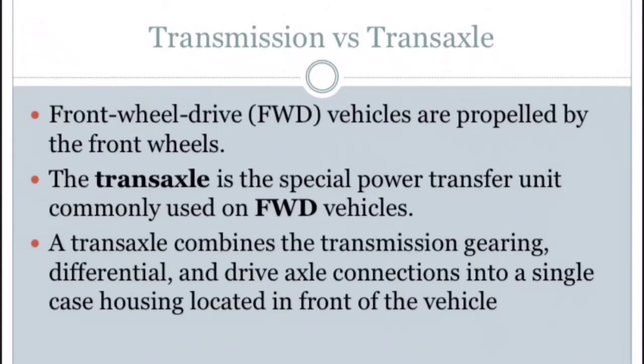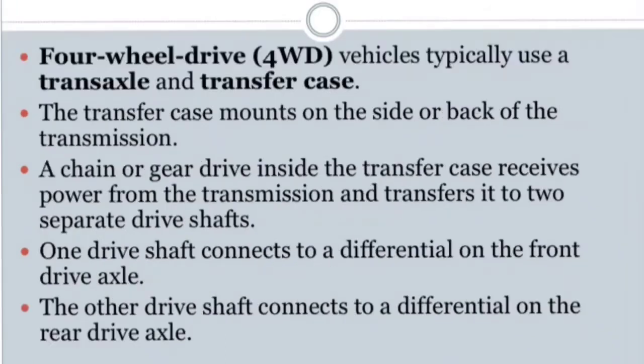The transaxle is a special power transfer unit commonly used on FWD vehicles. The transaxle combines the transmission gearing, differential and drive axle connection into a single case housing located in front of the vehicle.